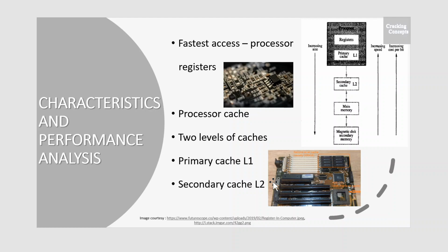It is implemented using static RAM chips. Including a primary cache on the processor chip and using a large off-chip secondary cache is currently the most common way of designing computers. It is possible not to have a cache on the processor chip at all. Also, it is possible to have both L1 and L2 caches on the processor chip.